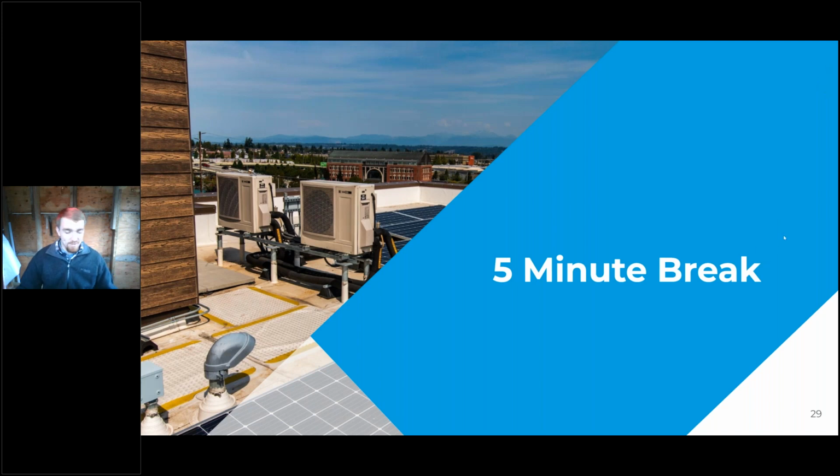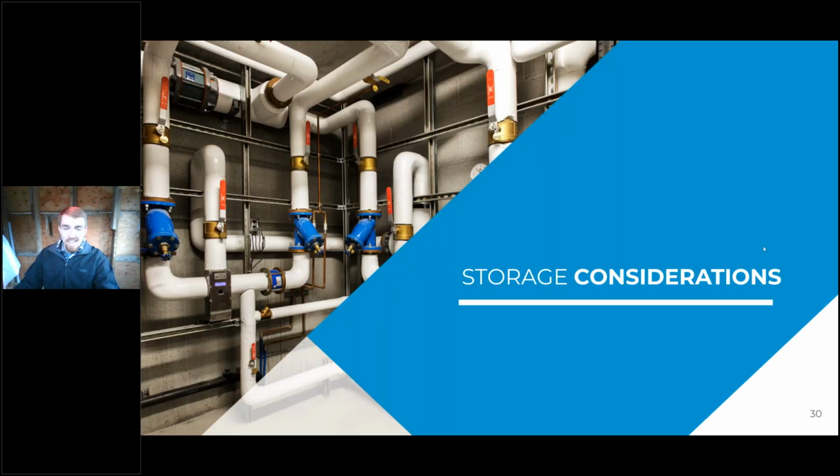So we had our 5-minute break, so we won't go to another. But now we can talk about the storage that's paired with these heat pump water heaters, which is actually really important because not only does it supply those really high peak demands when, say, everyone takes a shower at the same time, or all of this equipment's getting rinsed down with sanitized water, but it also allows the heat pumps to see the types of conditions that they like to see to operate most efficiently and reliably. So it provides that buffer to allow heat pumps to run for a long time, and the stratification in the storage tanks, depending on how we pipe it, will supply the proper supply temperatures that these heat pumps like to operate with.